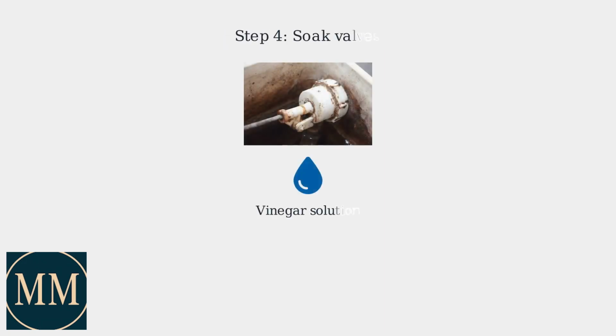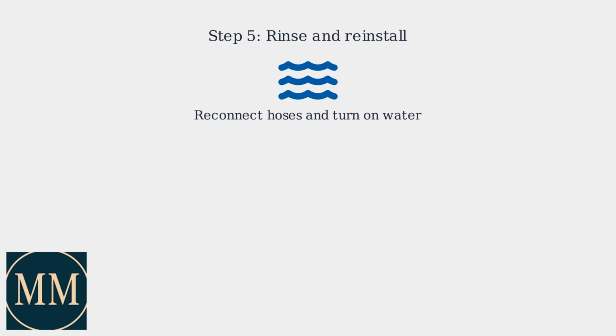Soak the valves in a solution of vinegar or a commercial descaler for about 30 minutes to dissolve mineral deposits. Rinse the valves thoroughly with clean water, then reinstall them back into the machine.